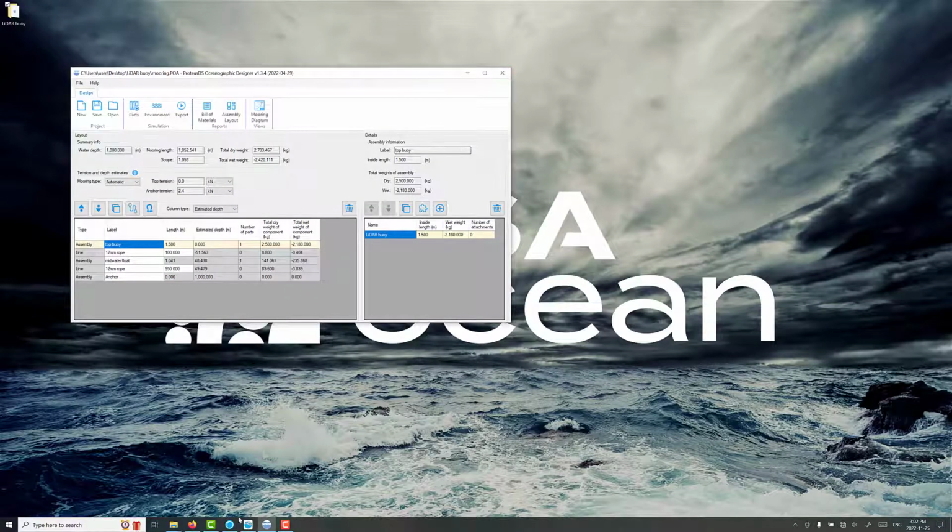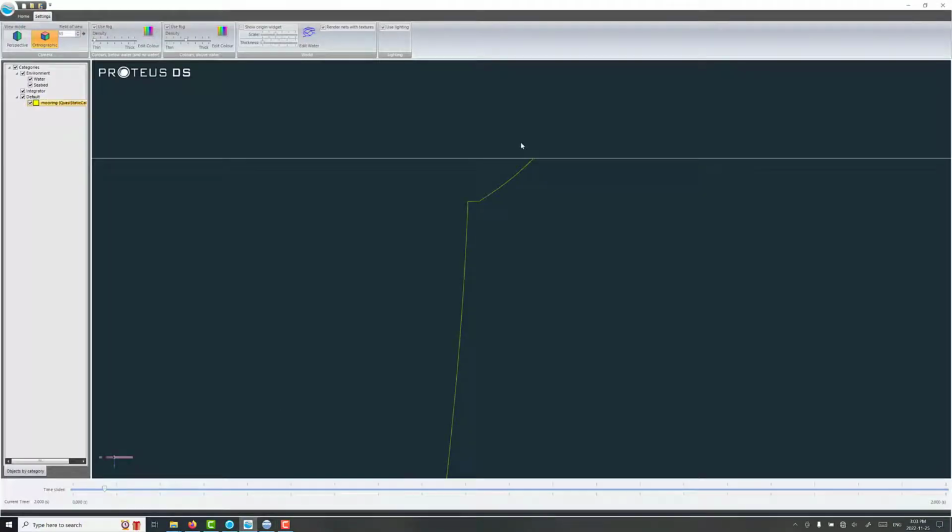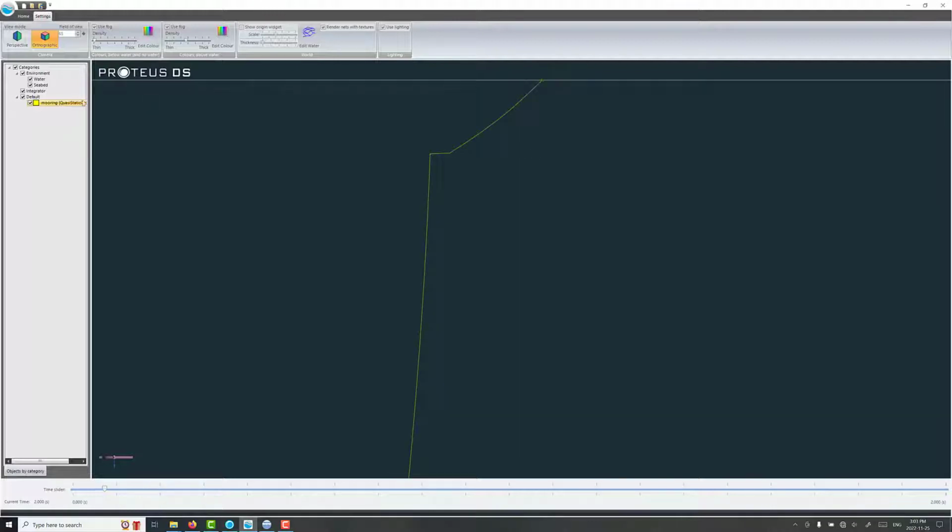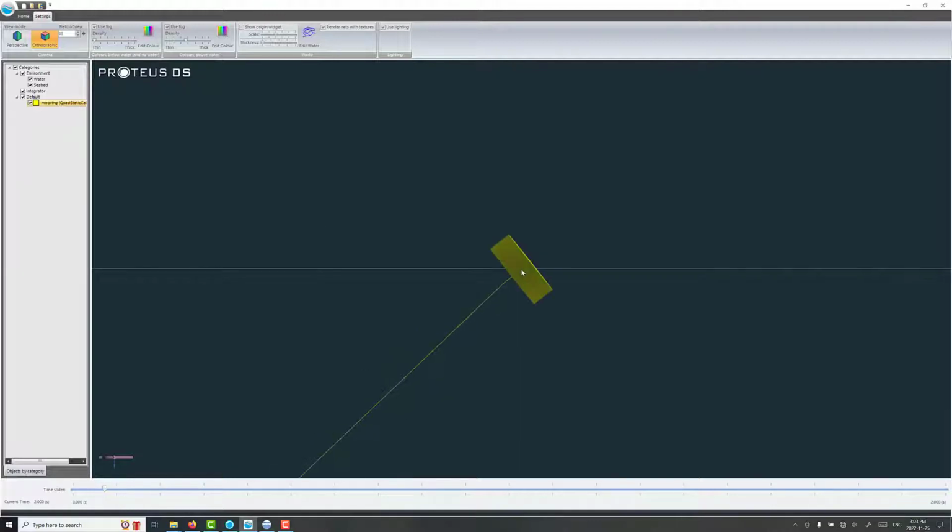Well, the problem here is that with a point model for the buoy, we don't model any of the dynamics of the orientation, and instead the orientation is taken from the tilt of the line angle. When there's lots of low tension in the mooring, you get a lot of tilt. It's not really realistically representative, especially for a self-stable buoy. So we need to replace this with a 6 degree of freedom rigid body model.